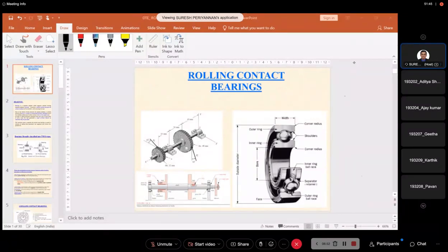Then we have to apply an appropriate lubricant. Only then are we able to obtain the appropriate relative motion between two mechanical components. When we introduce the fluid as a lubricant, it makes a film thickness between the journal and the bearing. We discussed the boundary layer thin film and the thick film.